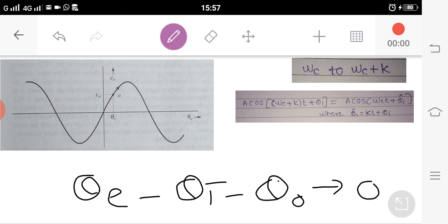If the input sinusoid is noisy, the PLL not only tracks the sinusoid but also cleans it. The PLL can also be used as an FM demodulator and frequency synthesizer. Frequency multipliers and dividers can also be built with the help of the PLL. The PLL, being a relatively inexpensive integrated circuit, has become one of the most frequently used in communication circuits.